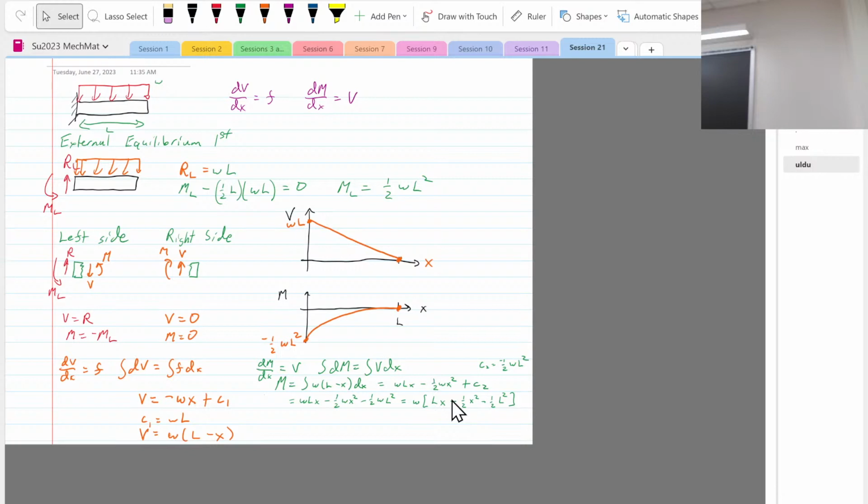Before we even get to drawing Mohr circle, we have to figure out very methodically which stresses we have, and how they're relevant to the bending moments or the shear force. Or it's a twisting problem, so what's the torque? Or it's an axial loading problem, so it's normal force. Or it's a pressure vessel, so you get stresses in two directions because of the internal pressure. That's how you approach Mohr circle.